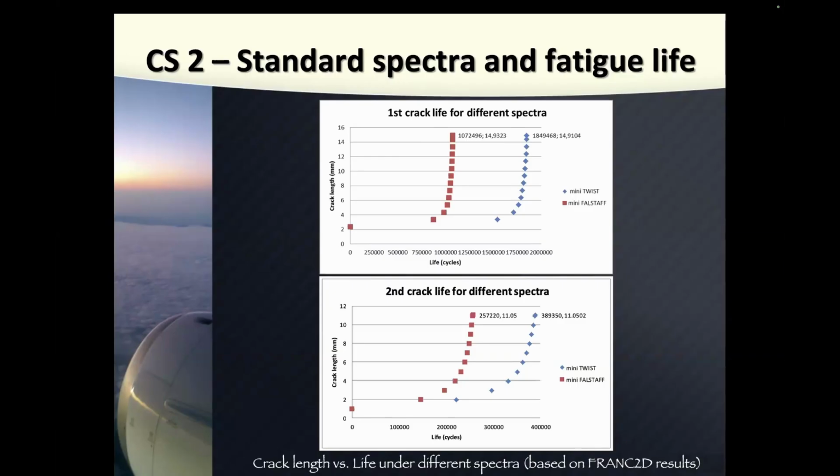So this means something like 200 flight hours, as far as I remember, which means that when you see that crack during some inspection or repair of the aircraft, and you see there is a crack with a length of 2 or 3 millimeters, then if you use my calculations, you will say, okay, in the next 200 hours we must do something, because in 200 hours it will fail.